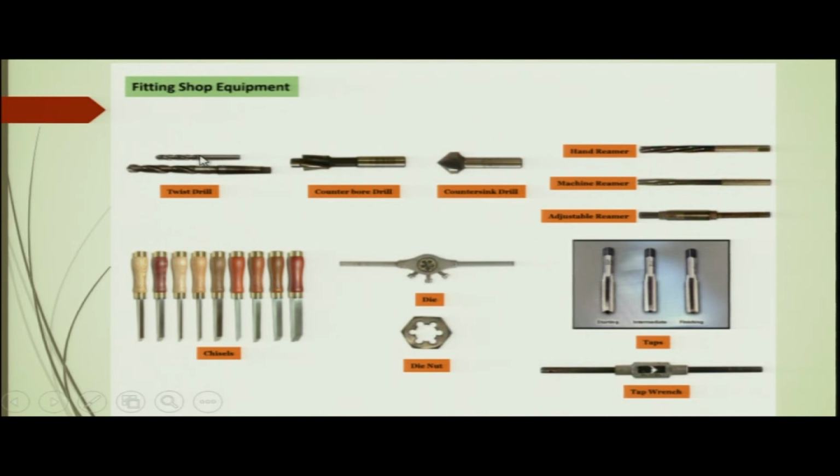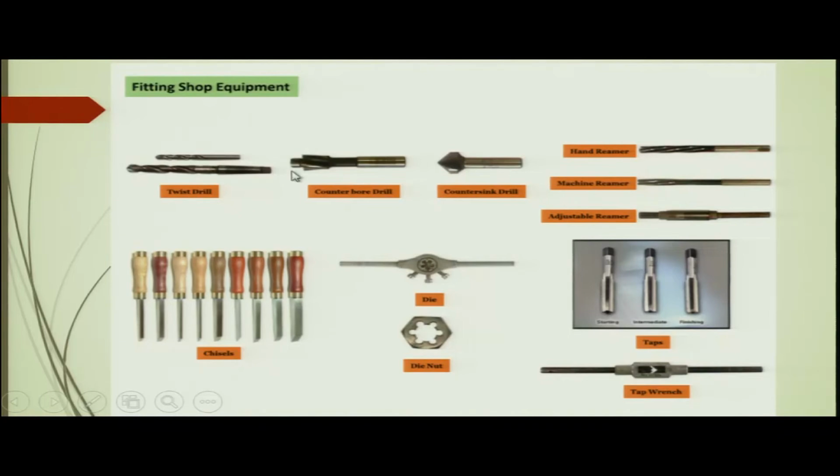So, the shank is made as a cylindrical shank, and that shank can be mounted on the holder not through the Morse taper, but through some other mechanism applied on the cylindrical shank. In particular, there is a groove and there is a spring loaded ball. That spring loaded ball will just be fixed in the internal groove and the hole made in the tool holder. So, this is just a snap fit, snapping the drill into the tool holder.